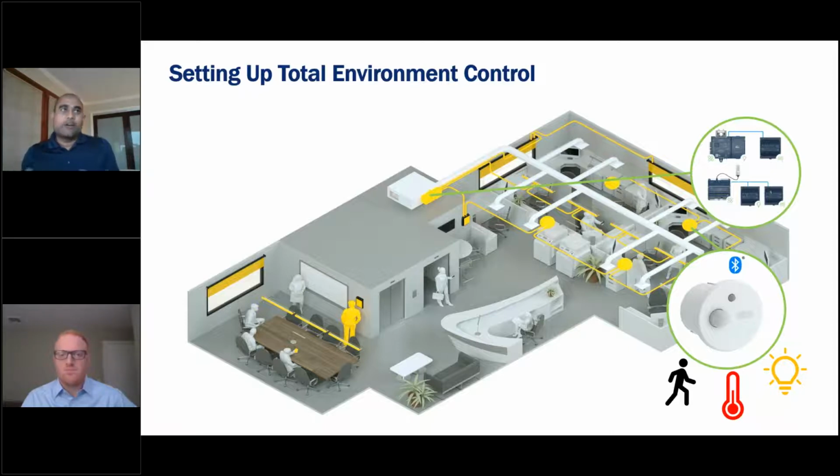And in this office, we wanted to have features like definitely a hands-free environment, environment control. We wanted to have room booking through Outlook and wayfinding to get your way around 3 floors of office space. So for this particular purpose, we picked out these BLE multi-sensors. They detect position, motion, temperature, and light intensity, and they communicate back to the controllers in the space, which have the embedded programming logic that manages the functions of the rest of the room.